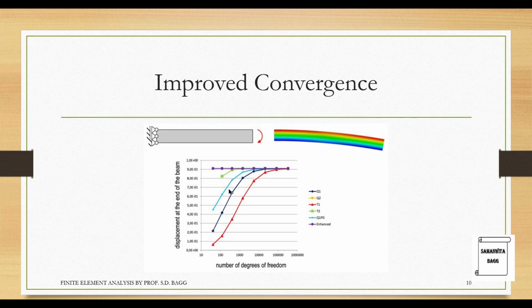So as you give more number of iterations for solving, you will get a particular solution. Now this needs to converge towards the exact solution. Say this deformation according to theory, which is the exact solution always, is say 0.02 mm. But when you are solving, you get a very high value. So as you increase more number of iterations for solving, that is, you solve the problems again and again iteratively, and you try to come to 0.02 mm as a solution.